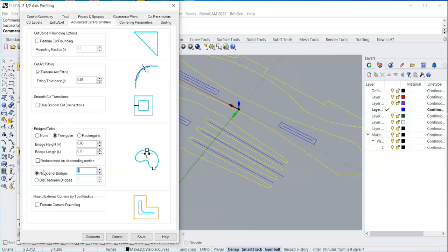Yeah. And you'll find this later on when we cut your wood pieces for furniture, our stool, you are going to have to put bridges in so those pieces don't fly out. And you'll also realize that different materials require thicker bridges. Like plywood needs a much thicker bridge because it's made out of ply. It's weak. It's not as strong as the metal.